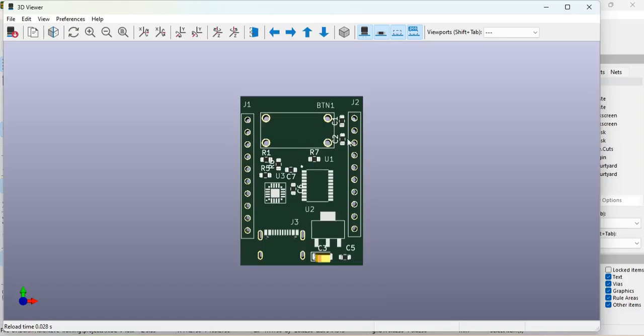Now if you can see here, this particular C1 and C2, the ref des of these is being overlapped by the button, so you might have to move C1 and C2 here. You can also see that R5 and R6 are slightly overlapping, and C6 has to be adjusted, and if required C3 might have to be placed a little towards or underneath this, moving this gap a little. Again, one point to remember: electrical performance is more important than the silk-related visual view.